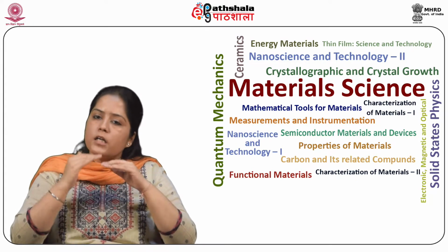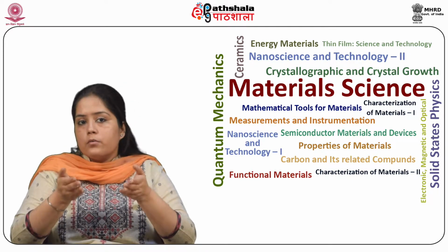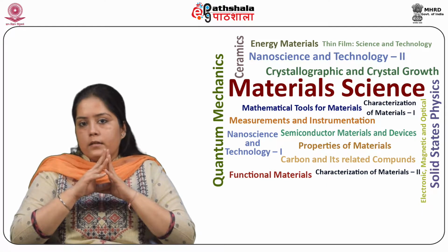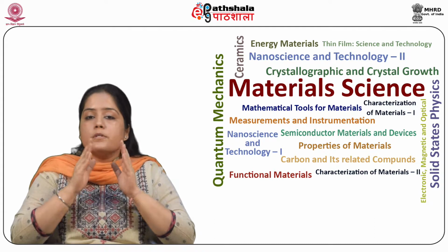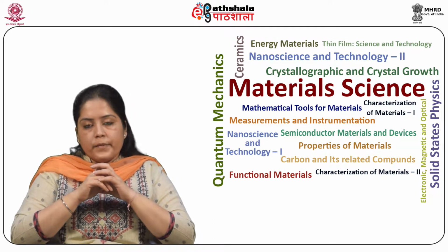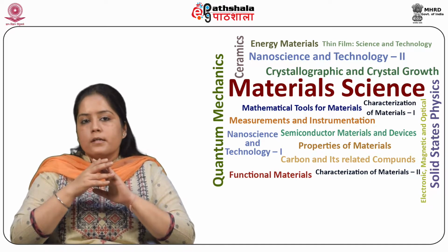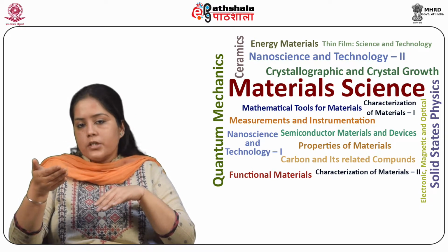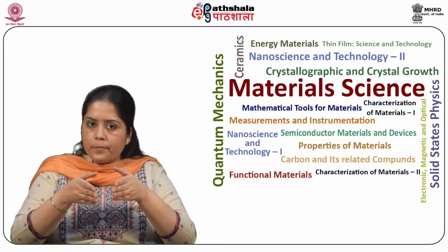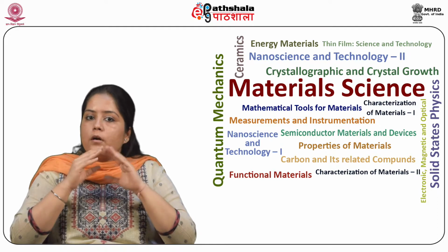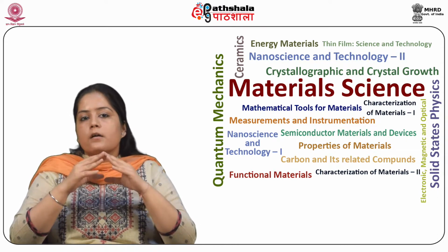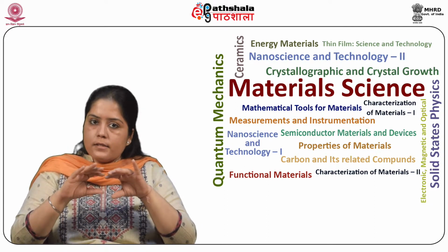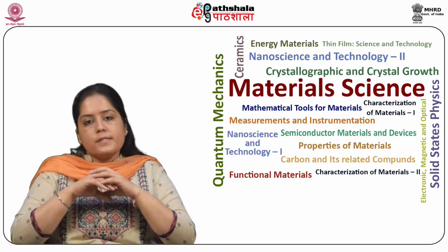They also contain ultra low levels of carbon, down to 0.005%. It is also called electrical steel because these alloys contain up to 6.5% of silicon. The commercial iron silicon alloys typically have up to 3.2% silicon, as higher concentrations usually cause brittleness during working operations such as cold rolling. In addition, one can add small amounts of manganese and aluminium, say up to 0.5%.